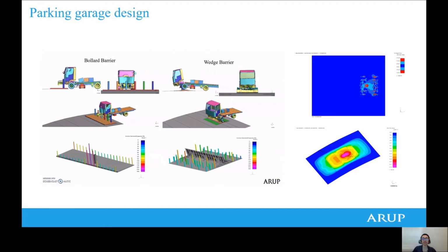By conducting this kind of impact simulation of different configurations, the maximum force transferred to the slab was assessed, and the stress and the deformation of the slab during the impact were also checked, as you can see here. And the anchorage design was conducted by varying the layout and strength of the anchorage in the simulation. So in this example, LS-DYNA simulation was directly used to provide important reference in the design problem and to help determine the dynamic demand on the structural system.